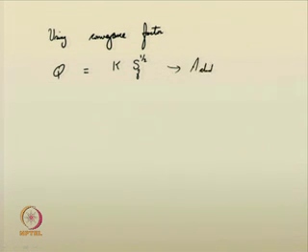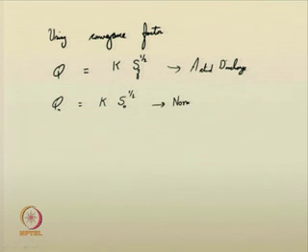So, this is the actual discharge. You can also give normal discharge using the bed slope. It is nothing but K S0 to the power of half. For a given depth, what is the normal discharge that can be identified? That given depth can become a normal depth using conveyance factor K and bed slope as the parameter.